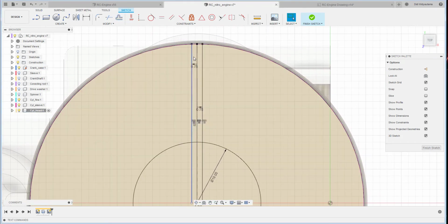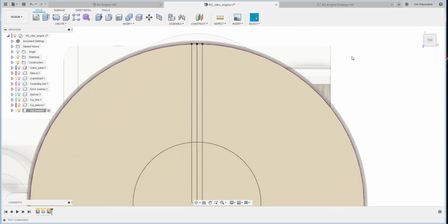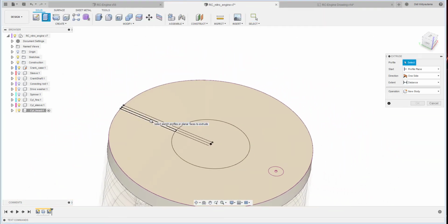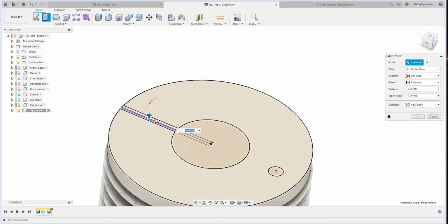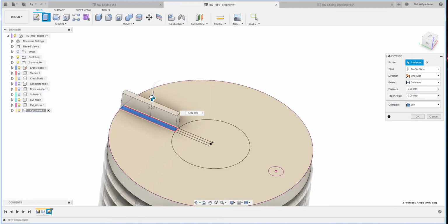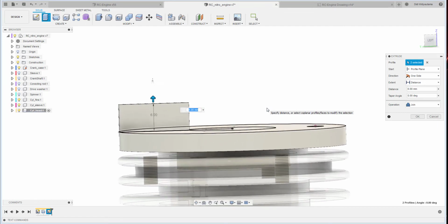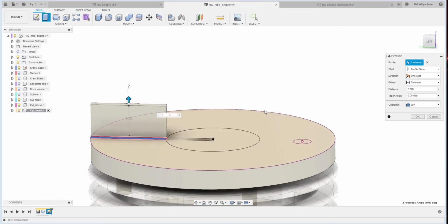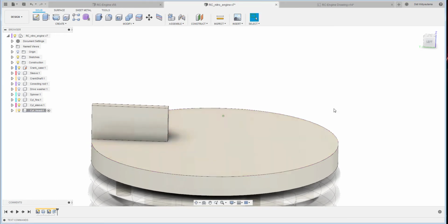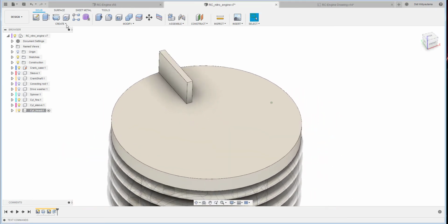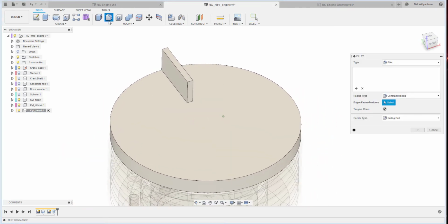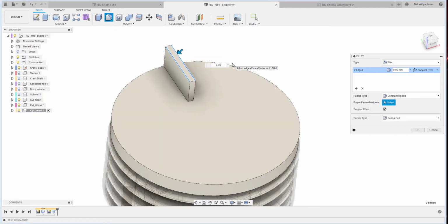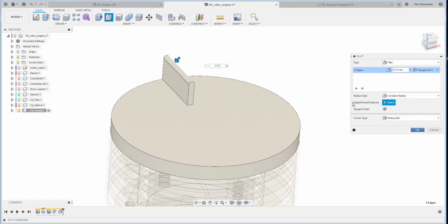and then from this area I will create the fins. Sorry, not that one, this one. Okay, so maybe the length of the fin will be 7. Okay, before that I would like to create a fillet here, 0.75. Okay,